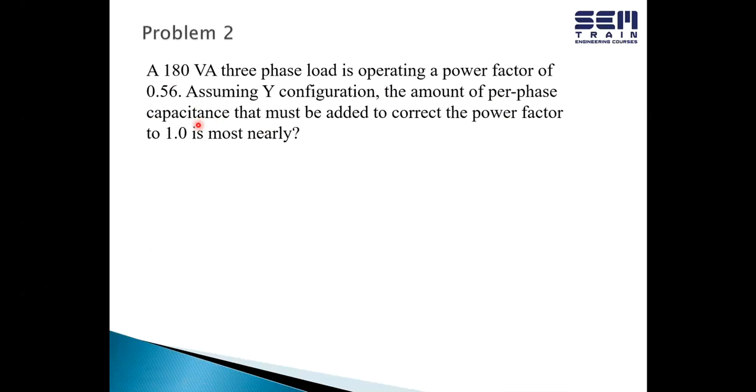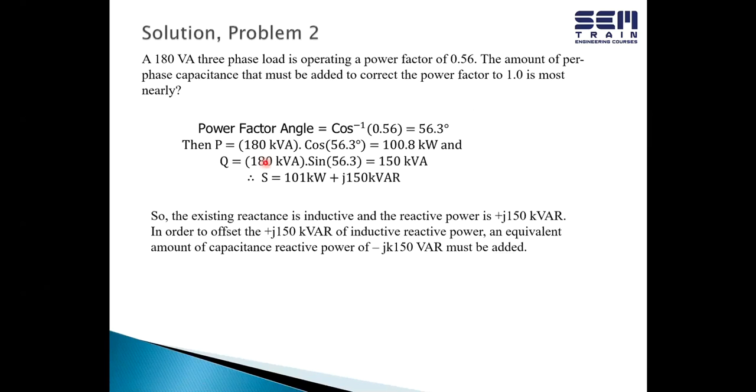But what we should do here is reformat this question and say in parentheses, in kVARs, because that's all you can find in the absence of voltage. All you can find is the kVARs correction, the amount of correction needed in kVARs. And that's what we're doing here.